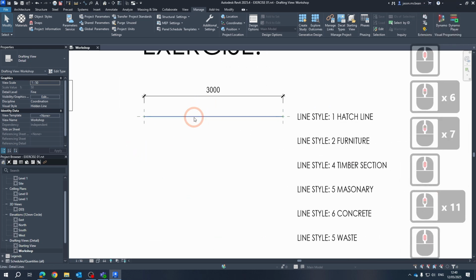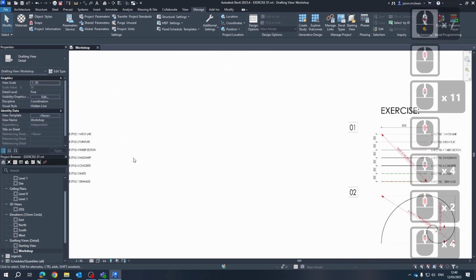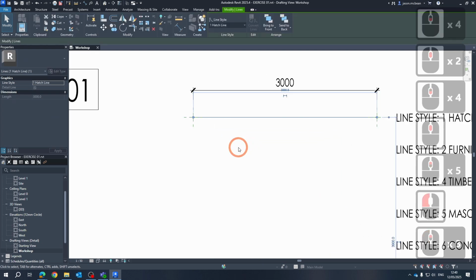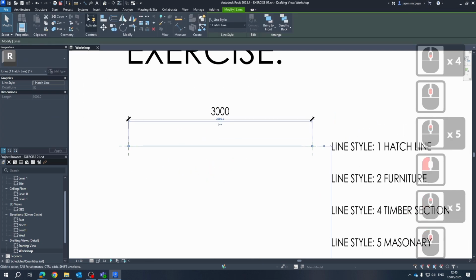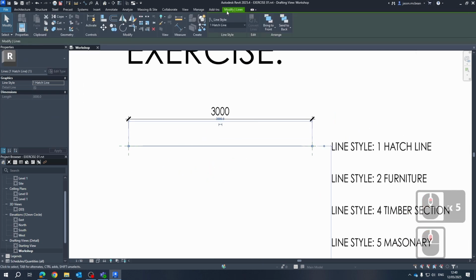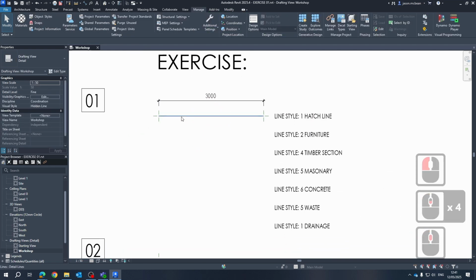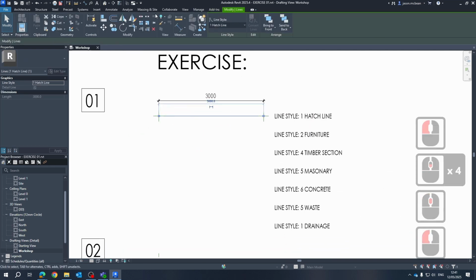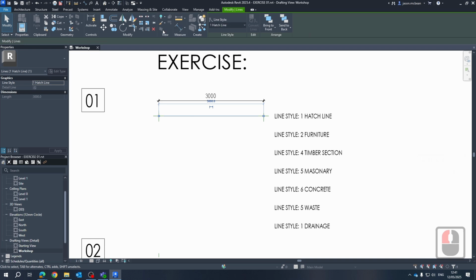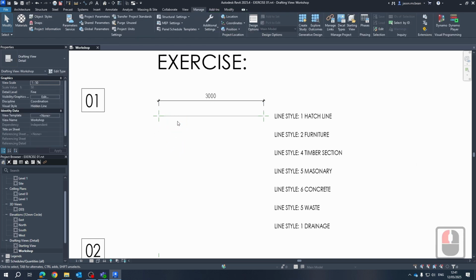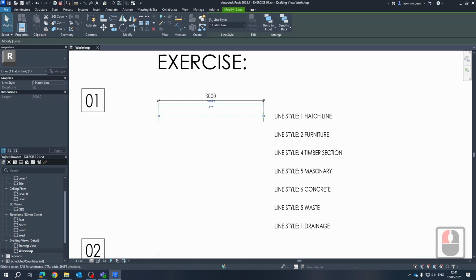Alright, so I've drawn my first line. Now pay attention to the spacing. I need to copy this bit of line work down. So when you select an object in Revit, a Modify tab will appear. So any tool or any line work or any object that we use in Revit will have specific commands and tools associated to that line work, item or family. So if I select the line, you'll notice now this new tab appears with a ribbon with all these different categories, controls, modify, view, etc.